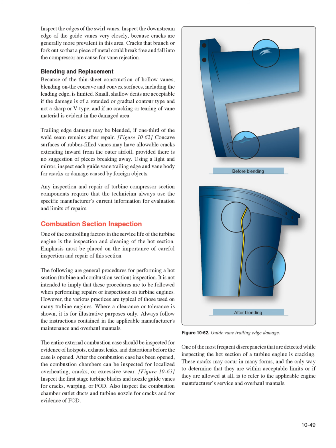Figure 1062, concave surfaces of rubber-filled vanes may have allowable cracks extending inward from the outer airfoil, provided there is no suggestion of pieces breaking away. Using a light and mirror, inspect each guide vane trailing edge and vane body for cracks or damage caused by foreign objects. Any inspection and repair of turbine compressor section components require that the technician always use the specific manufacturer's current information for evaluation and limits of repairs.